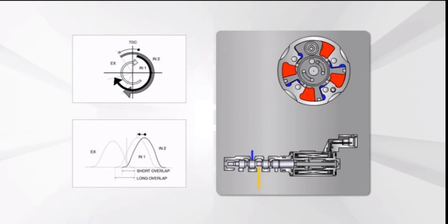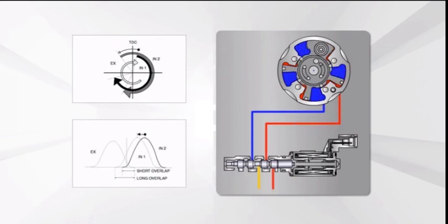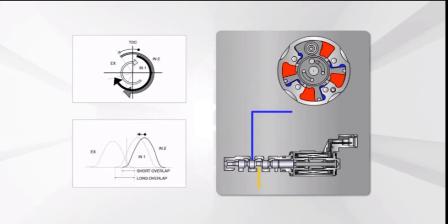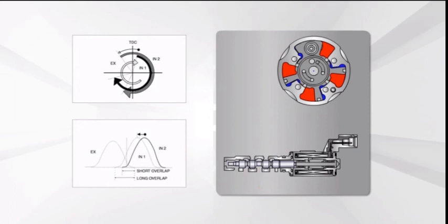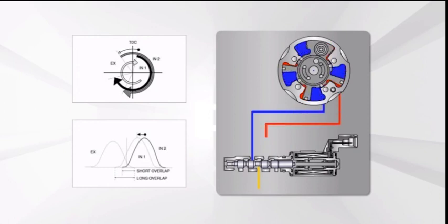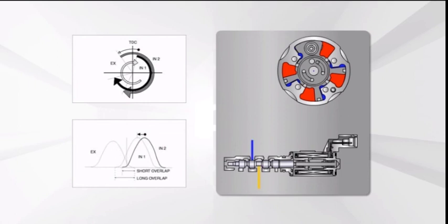First, exhaust gas does not contain the oxygen necessary to support combustion. Second, diluting the incoming charge reduces mixture density, which allows the air and fuel to burn more slowly. This causes a reduction in cylinder pressure and helps lower combustion temperatures by as much as 300 degrees Fahrenheit or 149 degrees Celsius. Because NOx output is relatively small at idle or when the engine is cold, no exhaust gas is recirculated under these conditions.